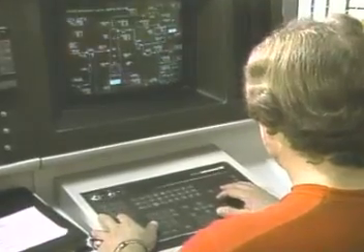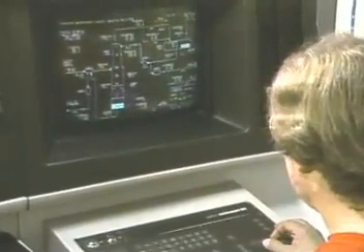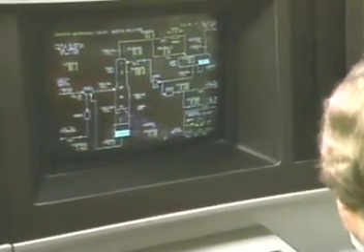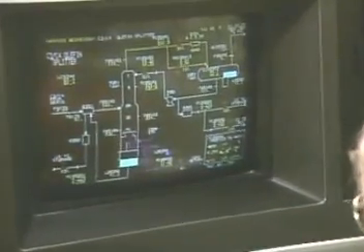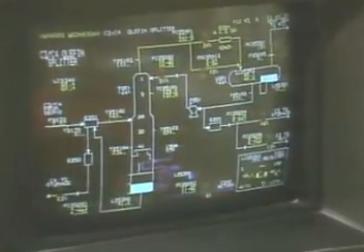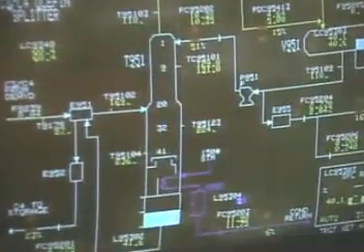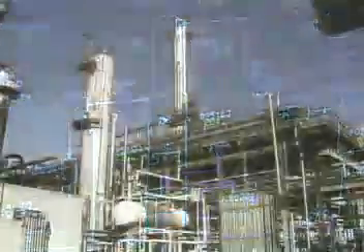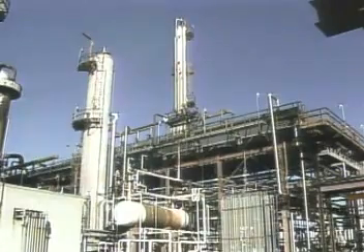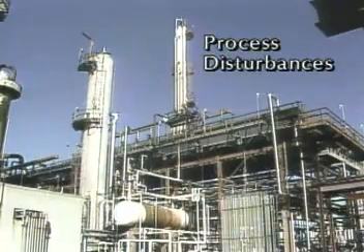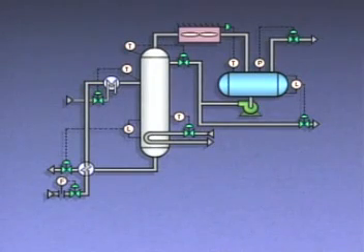The term steady-state operation describes conditions in a distillation system when the process variables are changing in small amounts within prescribed limits. During steady-state operation, changes in the flows of material and energy are minimal and are handled by the control system. However, major changes, called process disturbances, can affect the material balance and the energy balance. Many process disturbances result from changes in feed composition.